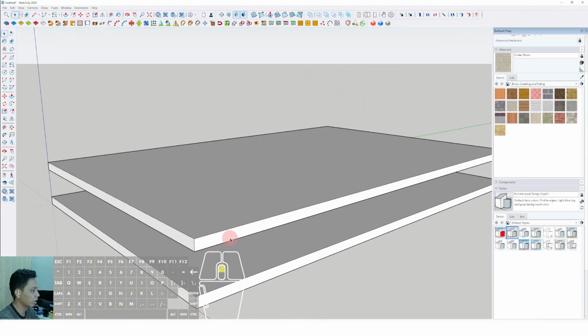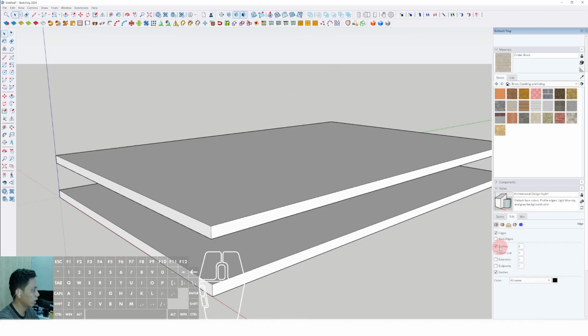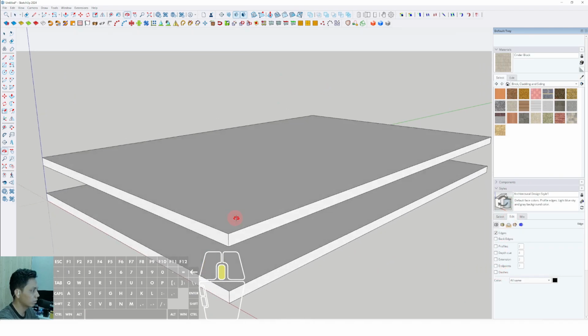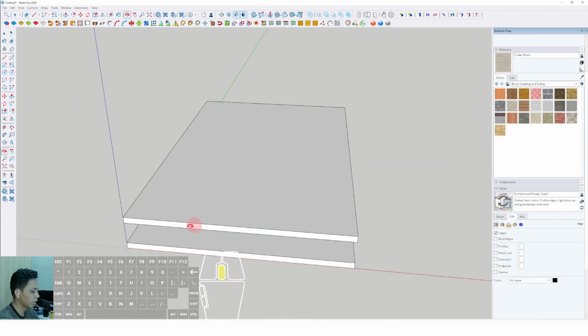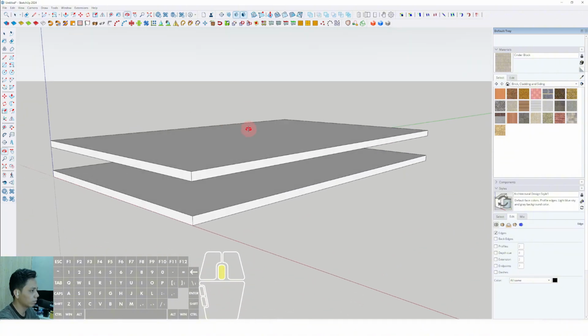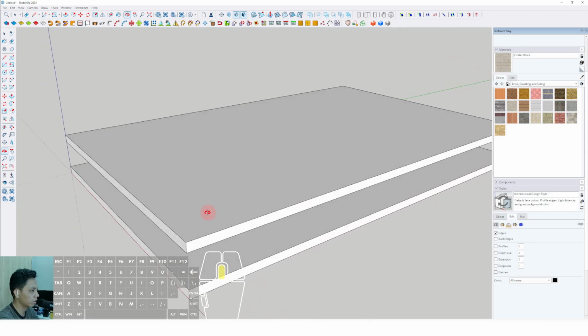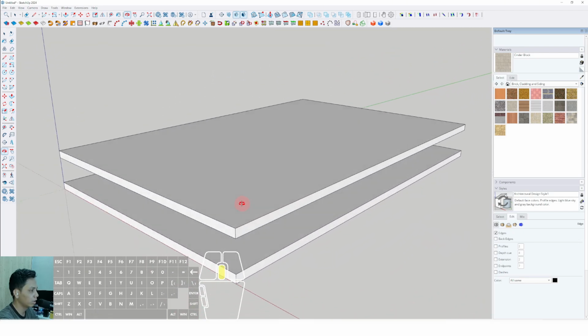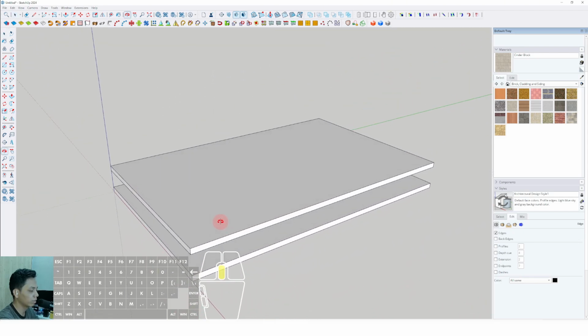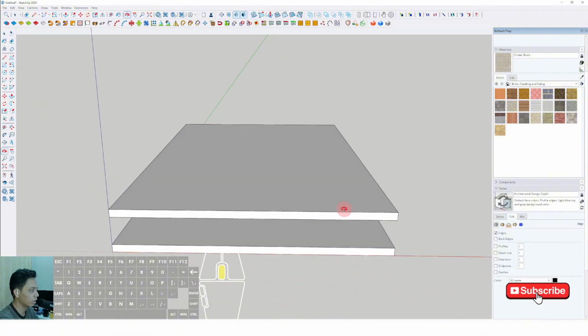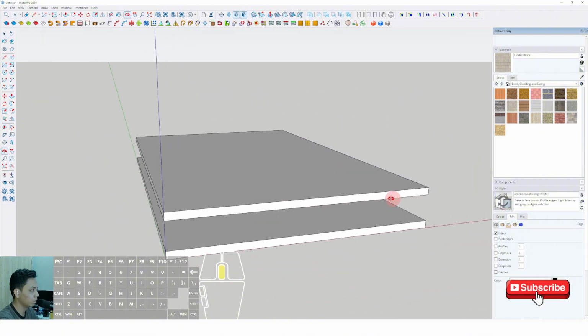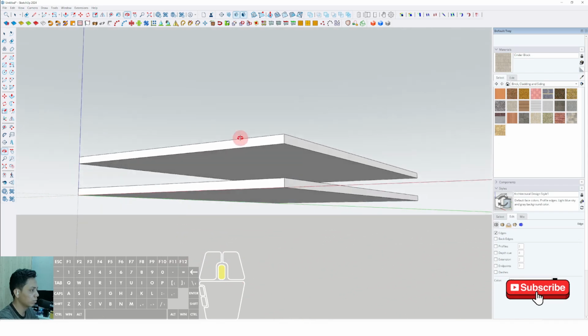Okay, and I will set the style to uncheck profile and dashes, so it could make the 3D modeling faster, because this decreases the performance of this 3D model image. Then it could increase the performance of 3D modeling speed.